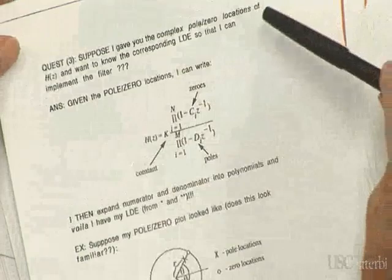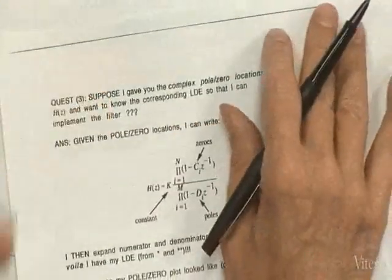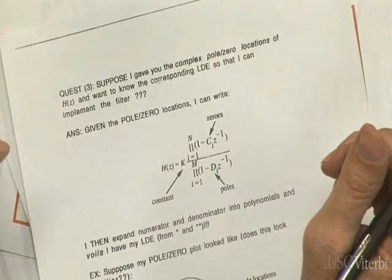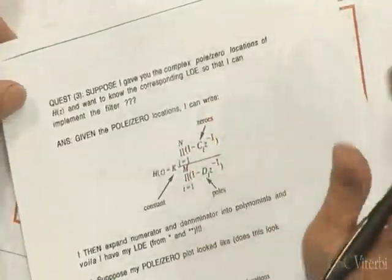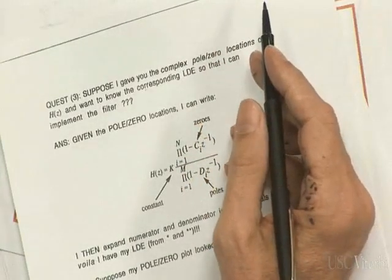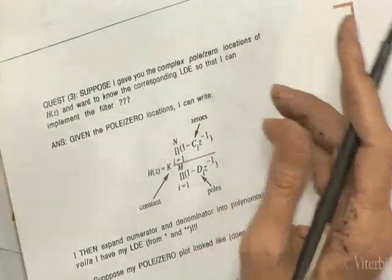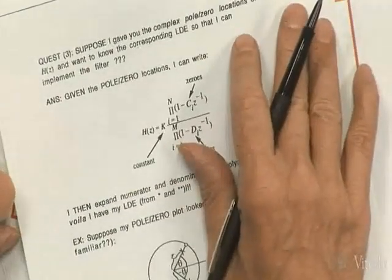Suppose I give you the complex pole zero locations of H of Z. Now, I know this may sound like it's off the wall. You want to know the corresponding difference equation. Whoa. Now, we still know it's causal. But I'm going to tell you that H of z has a pole at a certain location, a zero at z equal 4, whatever. And I know that it's a rational function of z inverse. Can you tell me what the difference equation is?